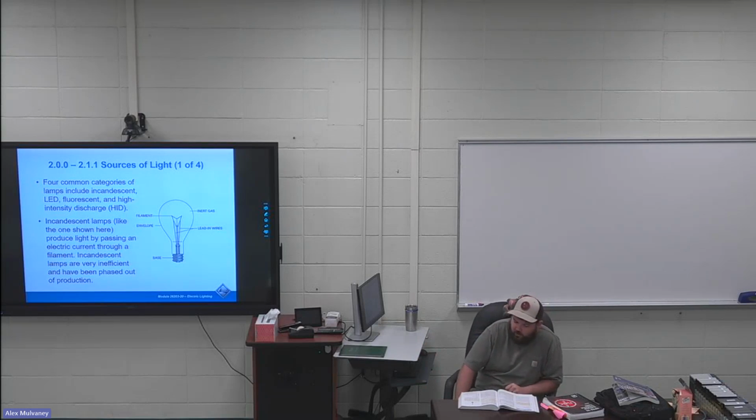Second bullet point is an online test question. A color temperature of 3500 K is considered moderate in tone, producing a balance between warmth and coolness. And the last bullet points that were highlighted: cooler temperatures of 4100 Kelvin and higher are considered cool in tone, or slightly biased towards blues and greens. So you need to know that 3000 and below would be considered warm, 3500 is a balance, and 4100 and above would be considered cool.